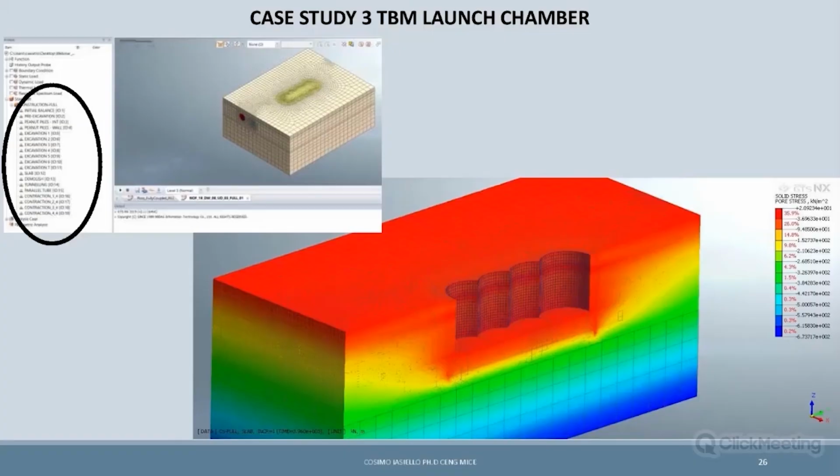So here, as you can see, in the fully coupled analysis we have all the phases in one stage set. We are not going to define manually which type of pressure applies to some mesh set or some node. No. We tell MIDAS, this is your water table in this stage.